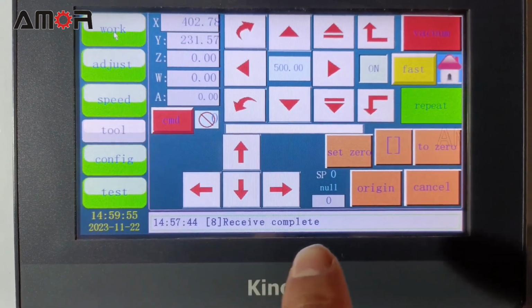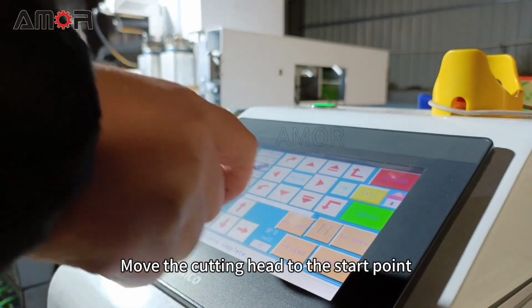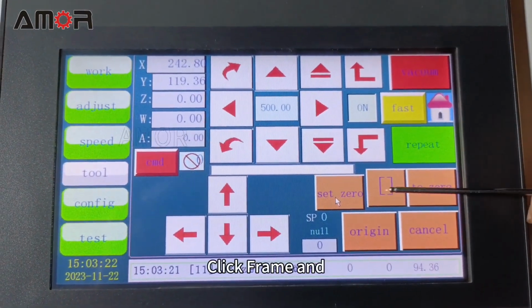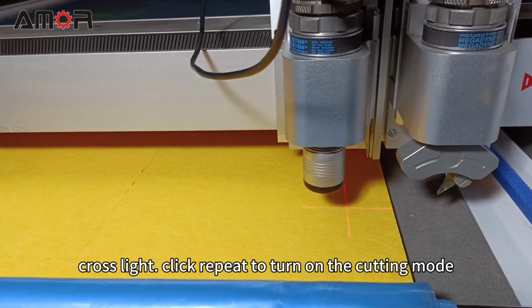Receive complete. It's displayed on the machine. Move the cutting head to the start point where you want to cut. Then click Set 0. Click Frame and check the cutting range by observing the position of the red cross light.